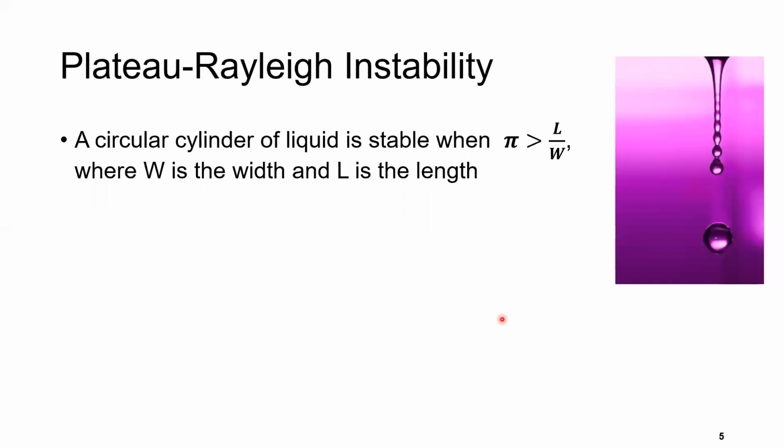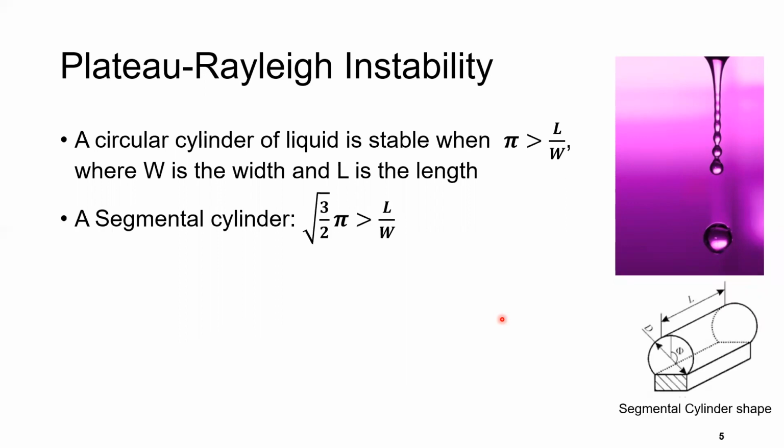In fact, this method of additive manufacturing doesn't really deal with the vertical cylindrical jet of liquid. We have more of a horizontal supported cylinder. And so that changes the stability criterion a little bit to give us some extra stability that's accounted for with that substrate underneath the track. Other laser welding studies have supposed that this critical ratio only needs to be less than 2 pi.